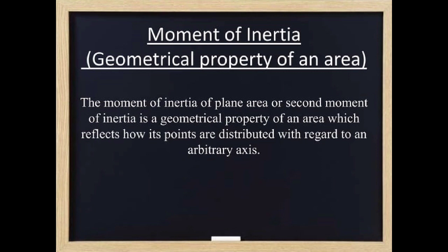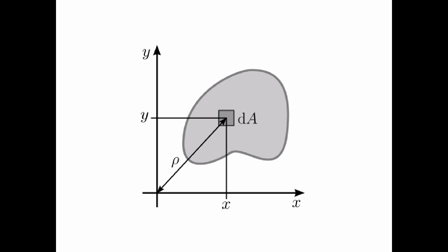Let us assume we have a wooden plank that we would like to use for crossing a canal. We can place the plank in two ways. One is flat, and one is with the shorter side of the cross section. Now we can tell that the plank will be stiffer if we put a load on the shorter side of the cross section.